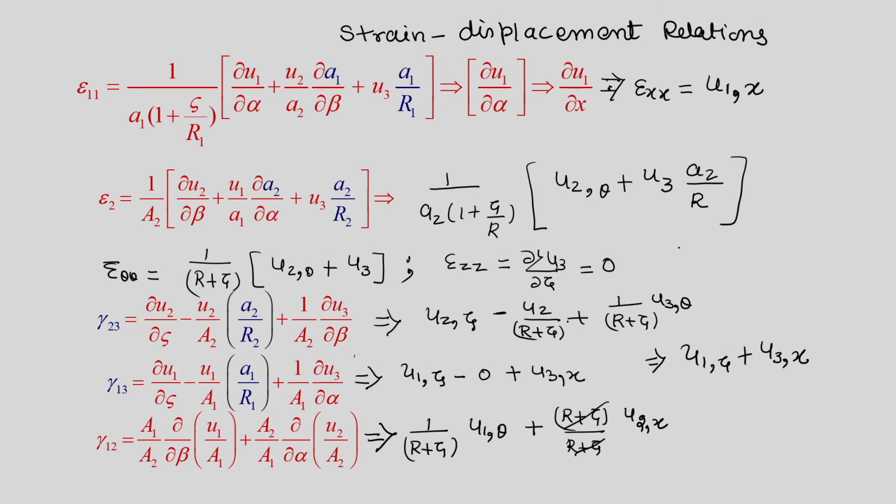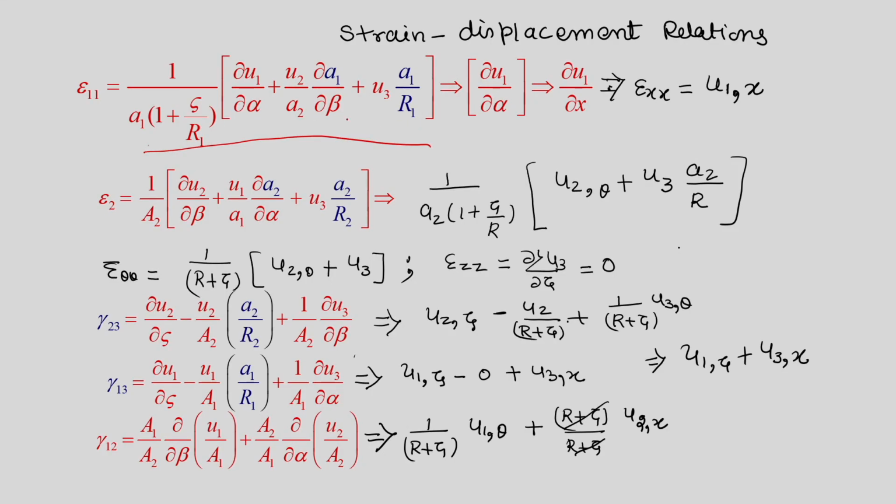There are two ways for a circular cylindrical shell. One way is that you can find the strain components generally given in the cylindrical coordinate system. In most theory of elasticity books, the strain displacement relations are given. So, one can use them directly, but I have already developed the strain displacement relations in very general form, so they can be found through a special case. Circular cylinder is a special case. So, putting the values of the Lamé parameters and radius, we can find out the strains.